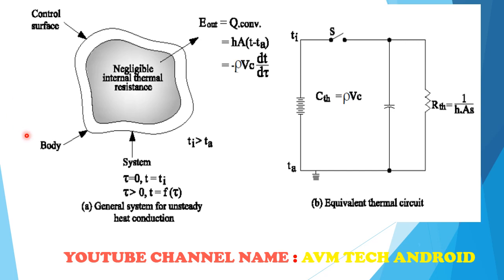So now you can see we are talking about a body. You can see the figure with A. This body is our general system, in which we have to go for analysis of unsteady state heat transfer. So we are considering this as a body whose physical size is small, and hence its surface area to volume ratio is high. For this kind of body, the temperature gradient is negligible, and because of that, the internal thermal resistance or conductive resistance is negligible.